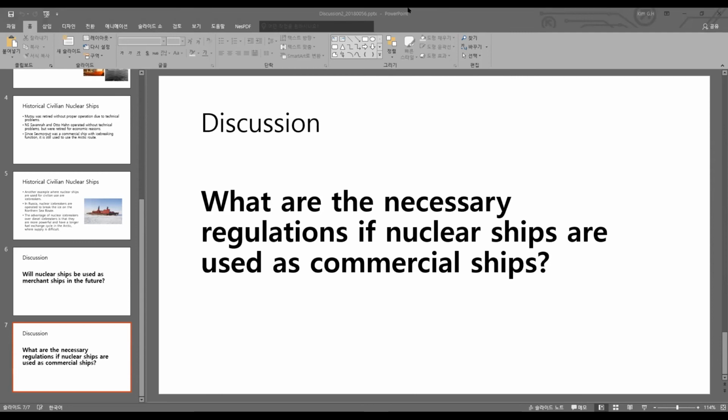So it is necessary to have a very strict design rule with a sufficient safety factor against the external force. In particular, most LNG ship fuel tank bulkheads currently use a double bottom, so it seems that reinforcement through triple or quadruple layers is necessary.